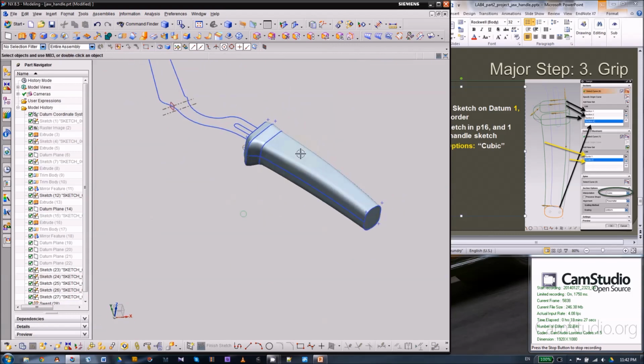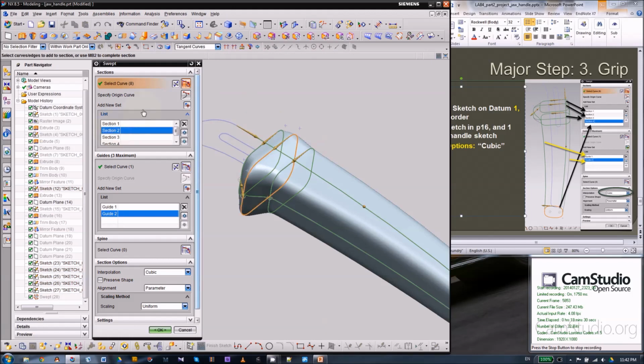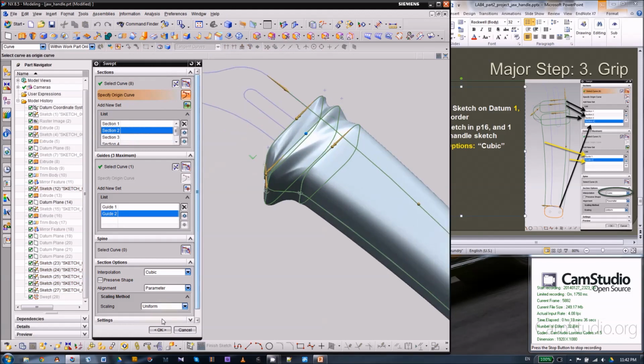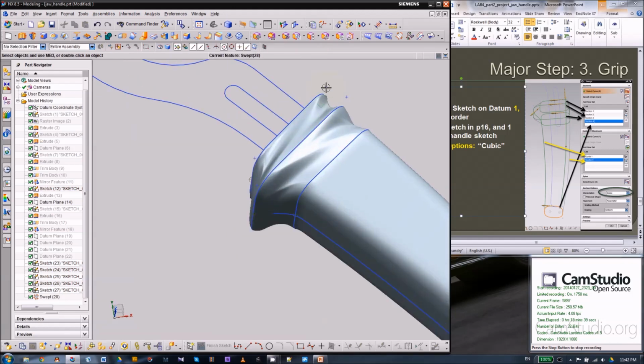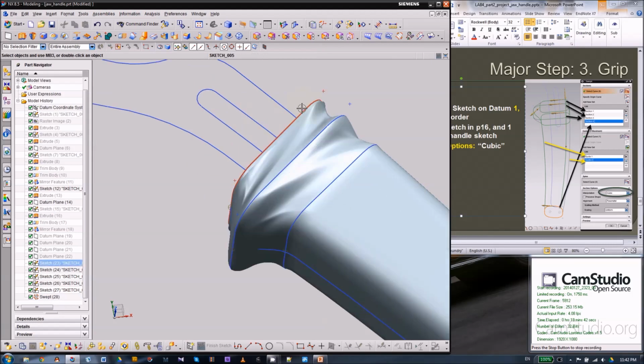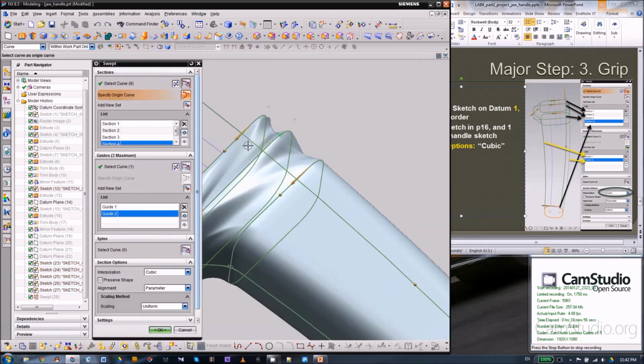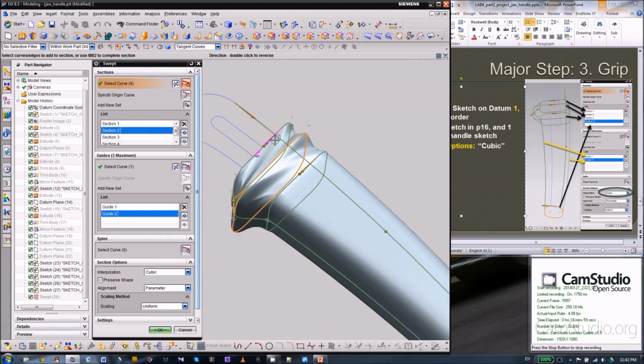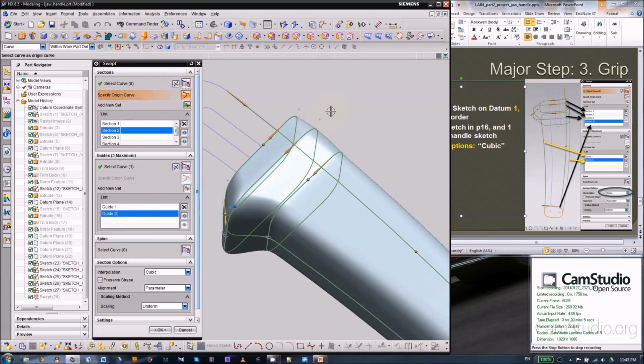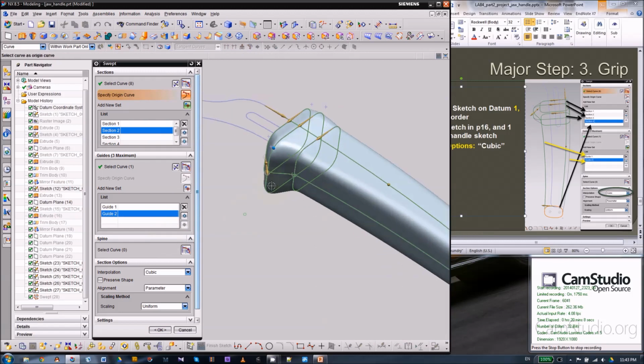Let's say one of the sections started from the wrong place, that's what happened. You can see the geometry actually scans from the end point of the straight line here. This line will match the end point of this arc. That's why it's all twisted. So just bear in mind you need to align the orange curve, on the second section as well.